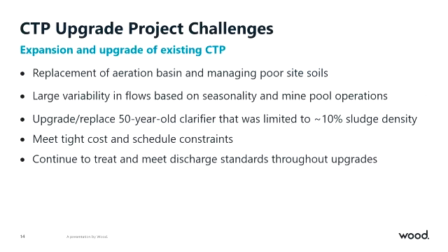So several project challenges we had to work through. Remember that aeration basin that was built up right in the middle, sandwiched in our project work area. Well, that was going away. Essentially, we had to replace it in its place, which was our work footprint. We also had poor site soils that we had to manage. So we had to preload several areas to build new concrete reactors and new thickener.